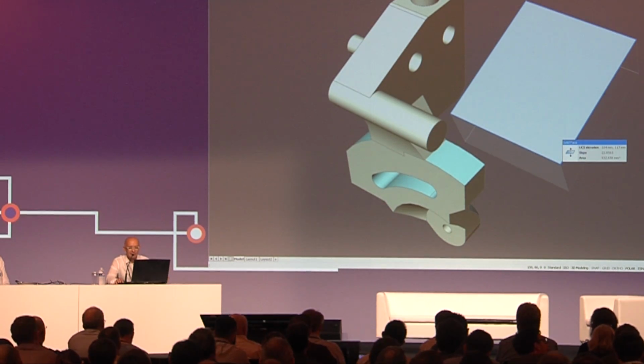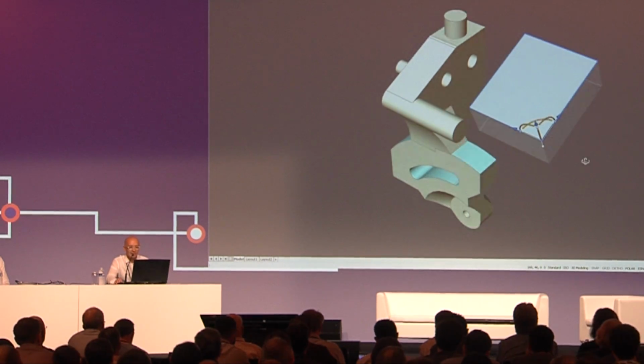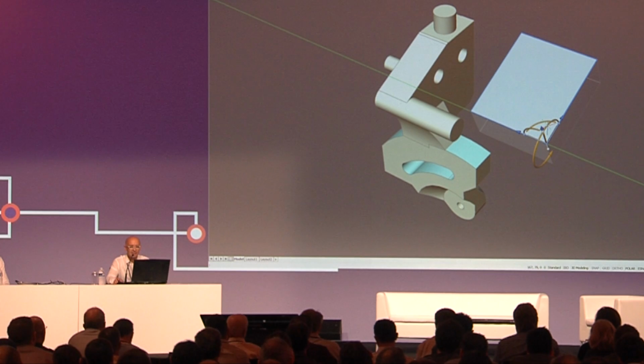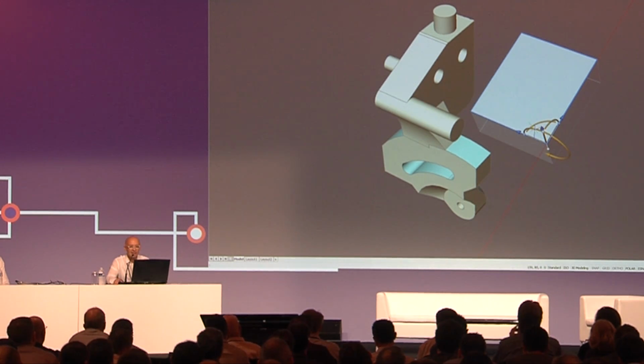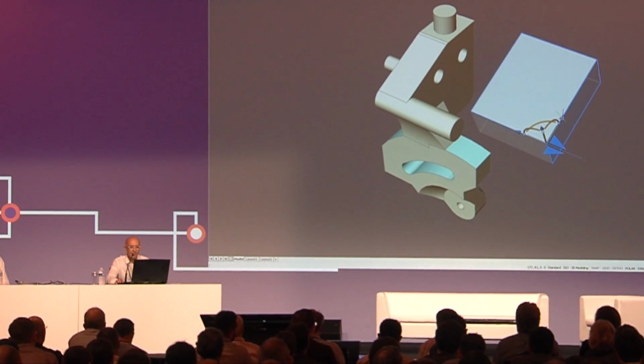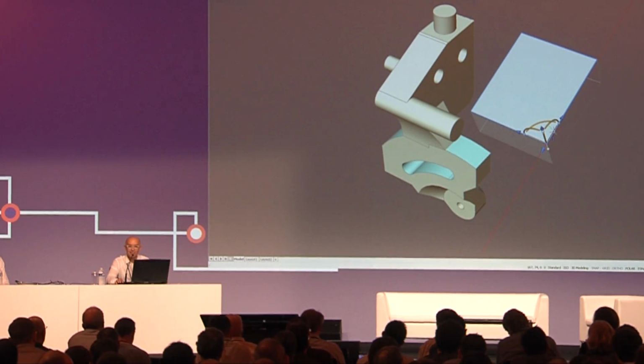Other stuff that is important in 3D is a new tool that we are introducing, and it's the manipulator. By slightly longer clicking, I get this control, and it shows you what it will do. Like, if I would click now, it would start a rotation about the green axis. If I would use this, it would start a rotation about the red axis. If I would use an arrow, it would start a mirror operation. Or if I use one of the tube-like elements, the straight tubes, I would have a move operation.